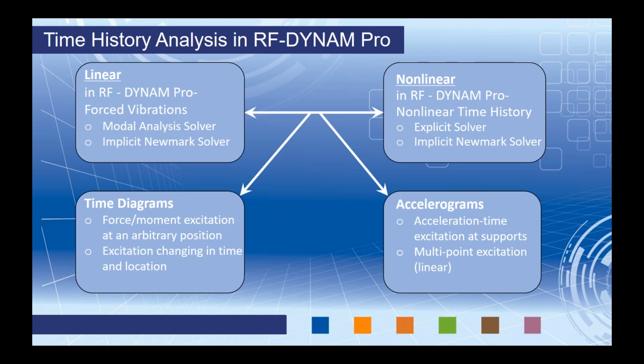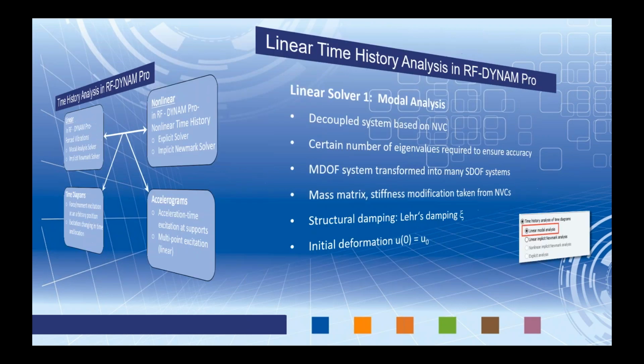Now, regardless of whether you're running a time diagram or an accelerogram, the display of results is available in a time course monitor, and this is certainly something that we'll be taking a look at quite a bit today. We can export the results into load cases for single time steps, so you can actually see the response of your structure at each individual time step back in RFEM, or we can export a result combination for the result envelope.